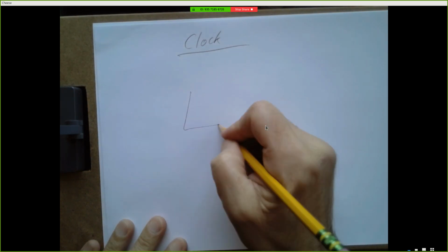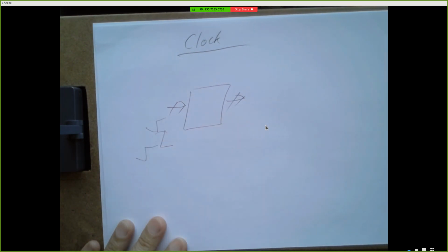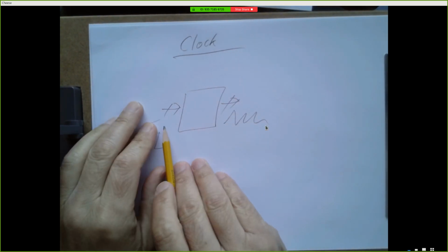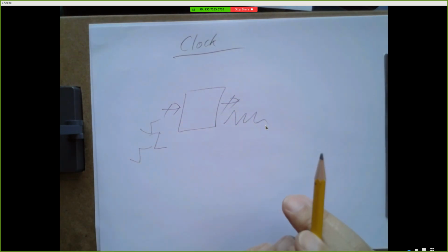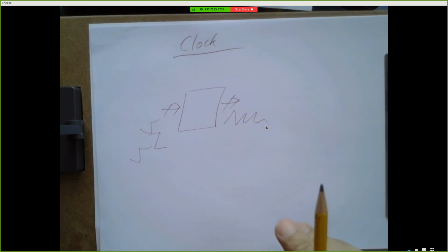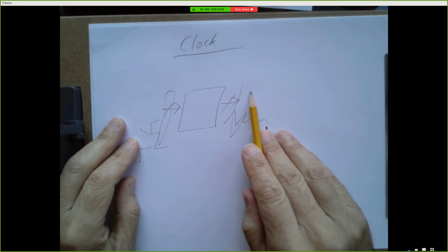And here's the idea. We have a circuit with some inputs and some outputs. And when inputs change, the outputs will bounce around. They'll go high, they'll go low, they'll move around to different values. But eventually they will stabilize. The idea is if you have a circuit like the circuits we've been building, for a fixed set of inputs, you can define what the outputs will be based on truth tables. They don't change. But it may take a while for them to get to those stable values because of the realities of physical chips. But at some point, if the inputs haven't changed for a while, the outputs will be rock solid.